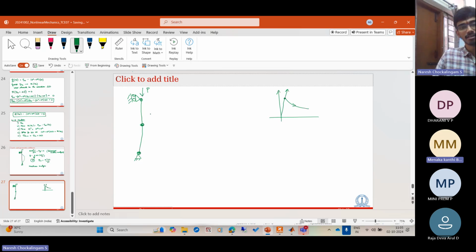So that's the idea. Now we have a buckled solution, but to trigger the buckled solution, we need a small bias. Even in real life, if there is no imperfection, if all loads are concentric, a column can remain straight even above its critical load. So the critical load is the point where you have two solutions simultaneously existing. But in reality, there are some imperfections. There can be some slight disturbing loads, which will cause the column to slightly go away from its equilibrium.